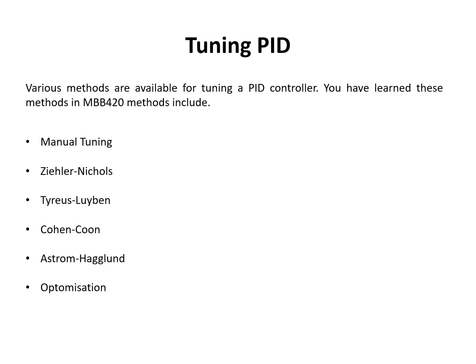There are other techniques as well which can use the actual experimental setup to design the controllers. Some of these techniques, which can be used either with an experimental setup or by using tuning methods in the Laplace domain, are Ziegler-Nichols, Tyreus-Luyben, Cohen-Coon, Åström-Hägglund, or using an optimization approach where you basically just iteratively change the gains using a gradient-based optimizer until you get the desired output response that you want, in essence.